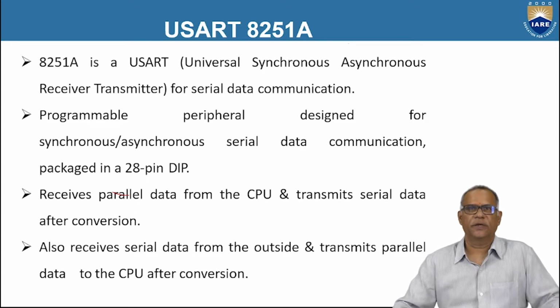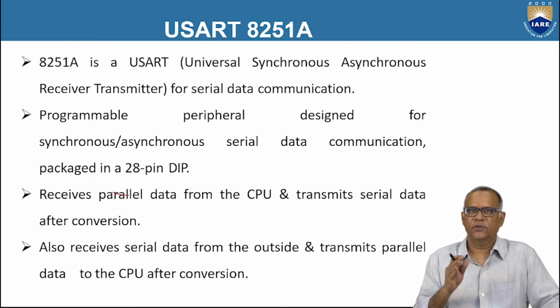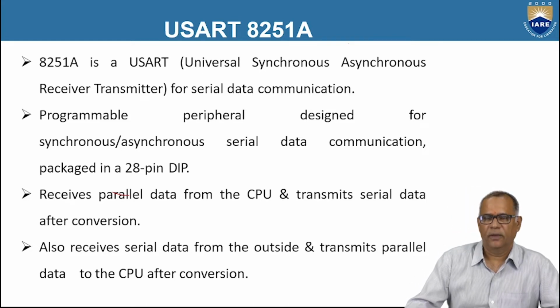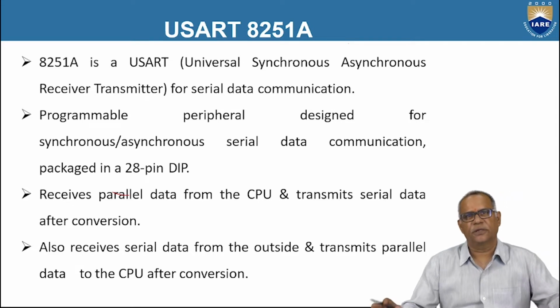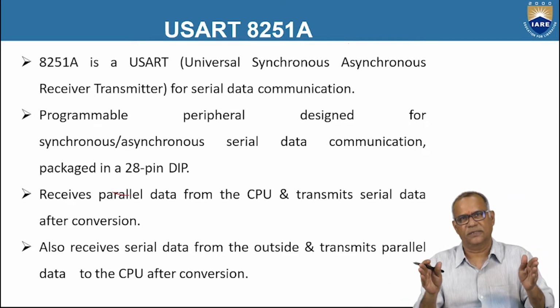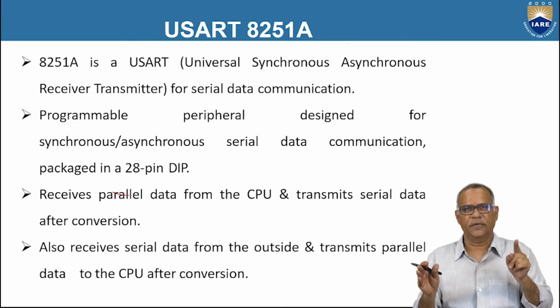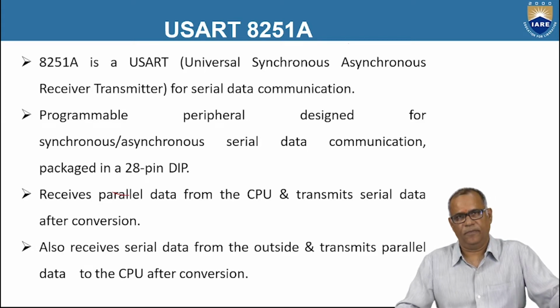In simplex communication, the communication is only one way. For example, the computer to the printer or the FM receiver. So here, the communication is only one way. Whereas in half duplex communication, the communication is both sides. So if A and B are the points, the communication can take place from A to B or B to A, but not at the same time. For example, walkie-talkie.